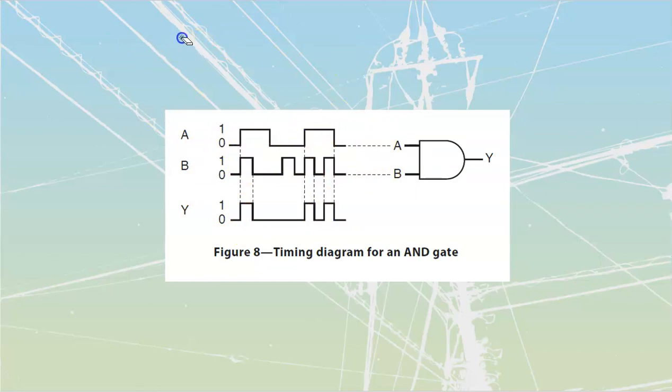Where this becomes really handy for us, and where we're going to see it a lot later on inside of motor controls, is if I'm looking at an output line, let's say this over here is an output line, I can define what turns this output line on. The way that we usually read them is backwards, not from following the inputs, but we look at the outputs and say what caused this to happen.